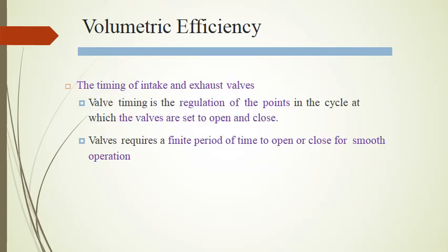The timing of the intake and exhaust valves. Valve timing is regulation of the points in the cycle at which the valves are set to open and close. Since the valves require a finite period of time to open or close for a smooth operation, a slight lead time is necessary for proper opening and closing. The design of the valve's operating cam provides for a smooth transition from one position to the other, while the cam's setting determines the timing of the valve.